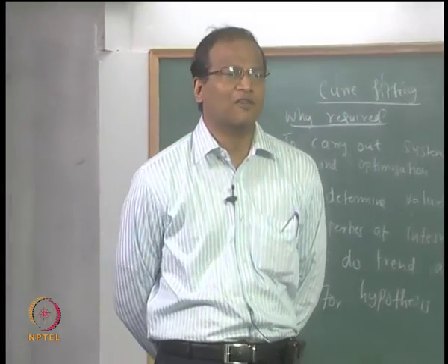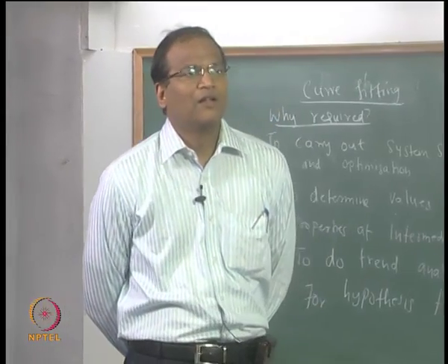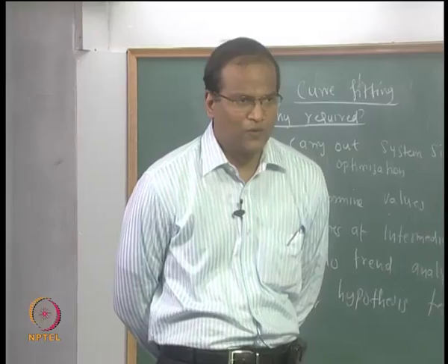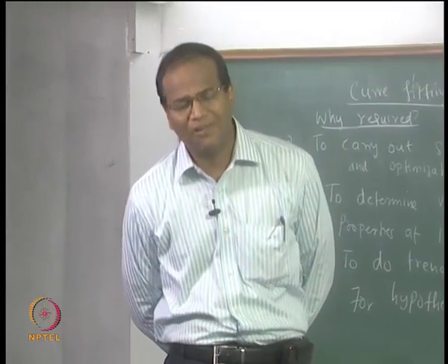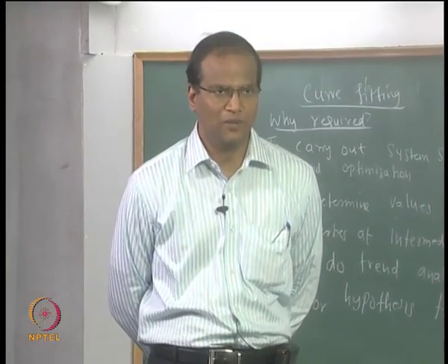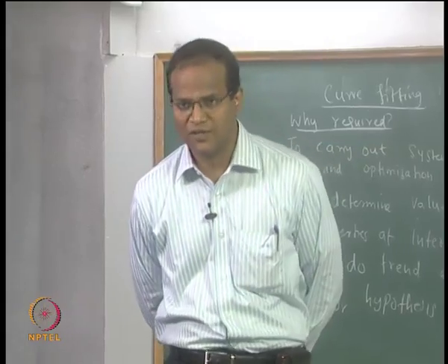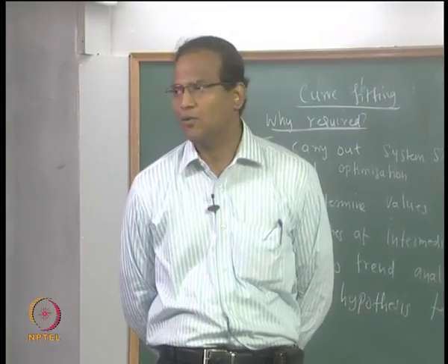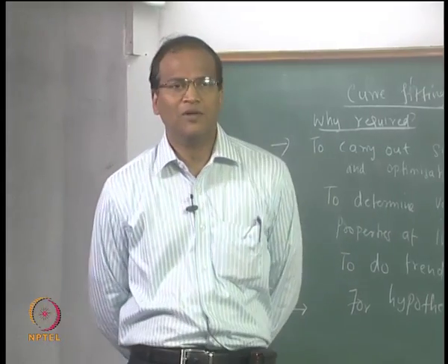So, for every Reynolds number find out the heat transfer rate. Heat transfer rate using Newton's law of cooling, convert it to heat transfer coefficient. From heat transfer coefficient get the dimensionless heat transfer coefficient called the Nusselt number. Plot the Nusselt number versus Reynolds number. If you so like, change the fluid from air to water, from water to liquid metals and so on.